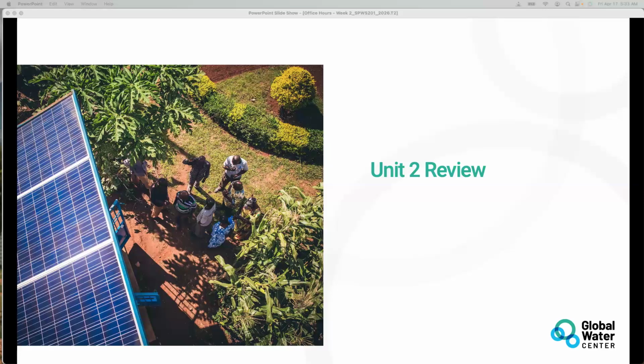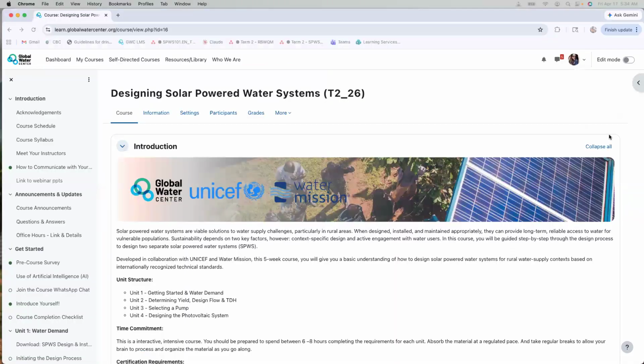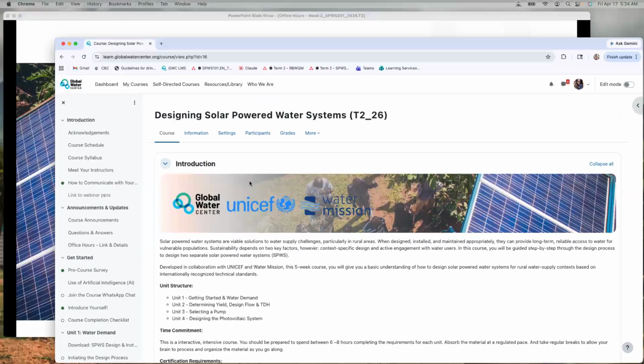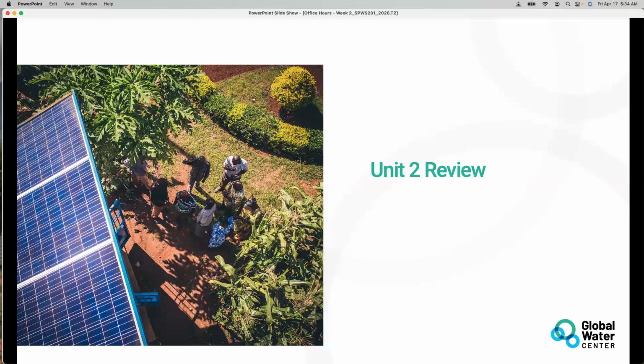So this needs to be clarified. The picture has no details on this one. The other one is, for example, on the same schematic, casing depth to screen is 70 meter. And below that, there is also a 12 meter screen. And below that, there is a 3 meter casing depth to the bottom.